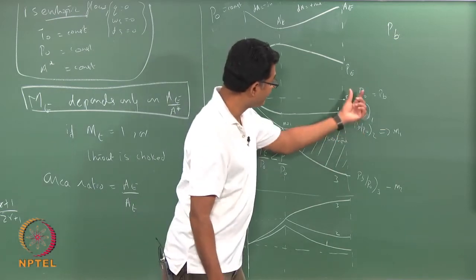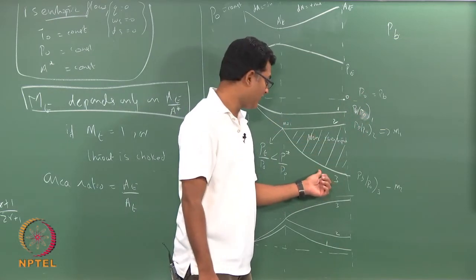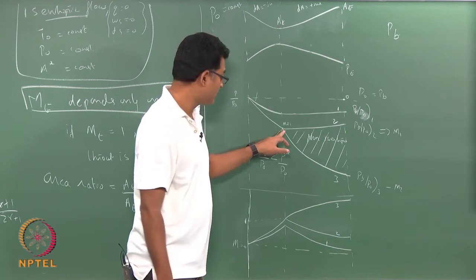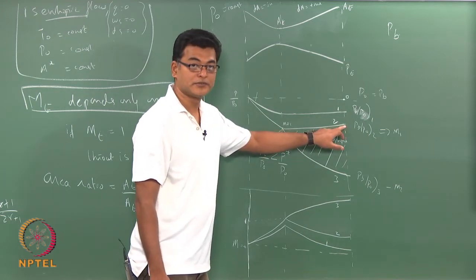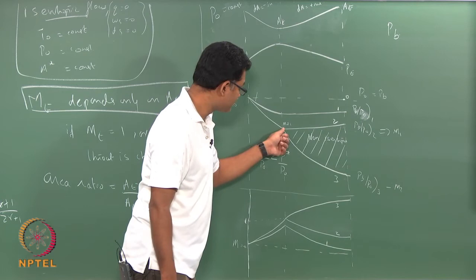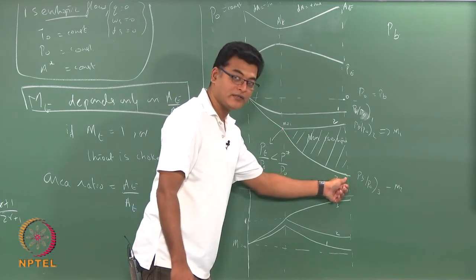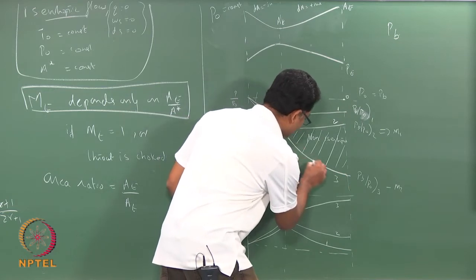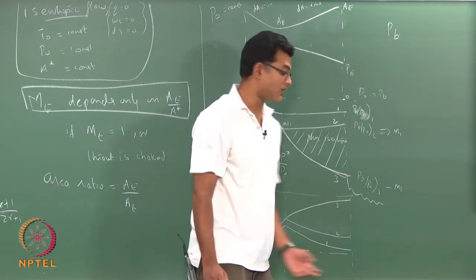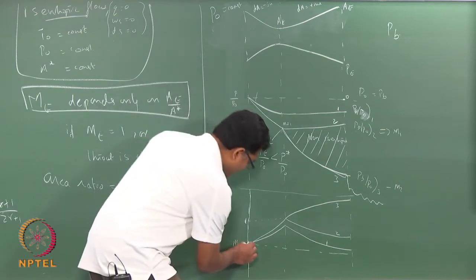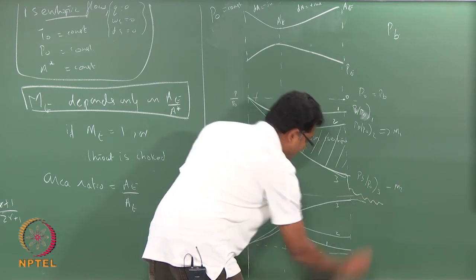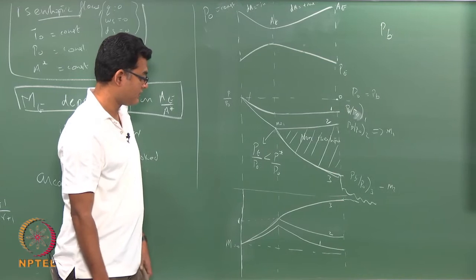So, I have reduced my Pb further than this. Okay. So, here what happens at Mach number 1, the throat condition is still Mach number 1. So, it can go to subsonic flow if the pressure ratio is this, but now we have reduced it much further. So, the pressure ratio would be this line plus, so it would take the same line as this and then do something at the exit to reach the reduced Pb. Like that it will go through the same curve here up to this point, and then it does something outside the nozzle to get a different curve.